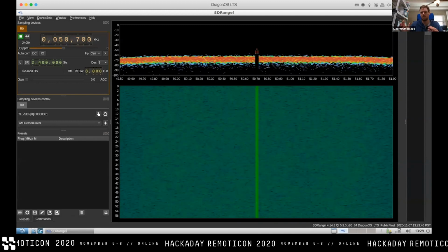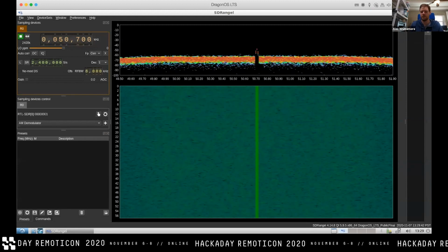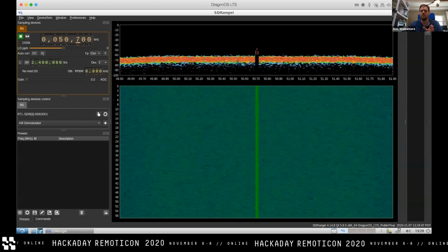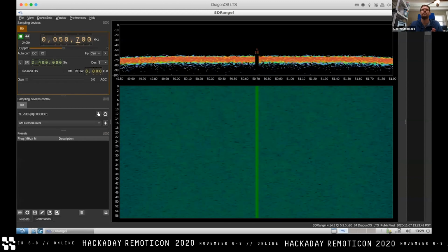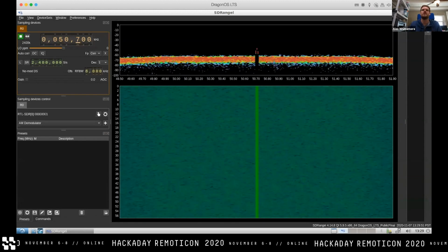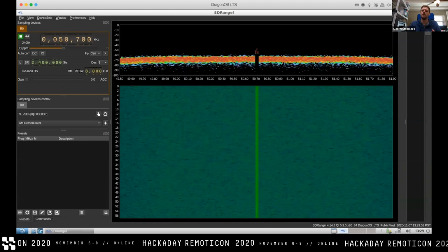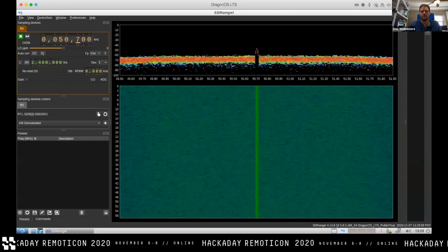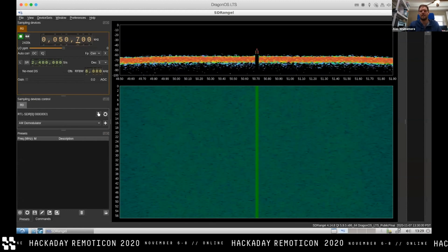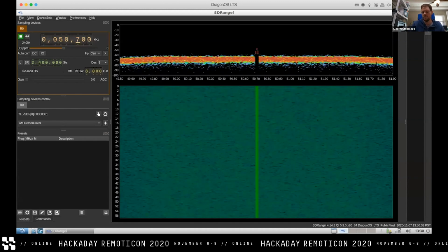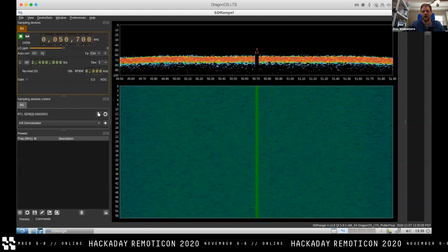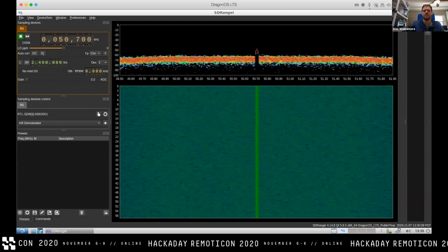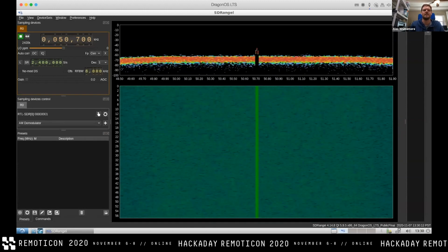So the 2.4 gigahertz we all know and love for Bluetooth Low Energy and regular Bluetooth and Wi-Fi exists between 2.400 gigahertz and 2.480 gigahertz. I'm sure it's slightly off of that. Anyway, it's 80 megahertz wide, which means that this SDR can't tune all of it at once. So it's not useful for that. And it also is too high. You can only go lower than that. It is useful for something like ADSB, which has a much narrower signal bandwidth and is at a much lower tuning frequency.